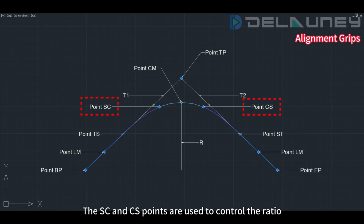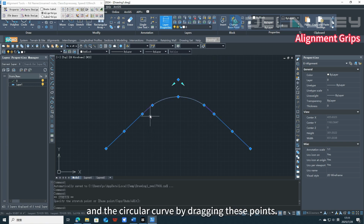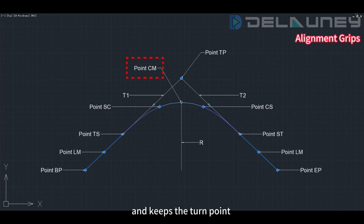The SC and CS points are used to control the ratio of the clotoid curves and the circular curve. You can change the length of the clotoid curves and the circular curve by dragging these points. The CM point is used to adjust the circular curve radius and keeps the turn point in tangent line position unchanged.